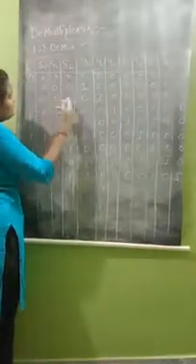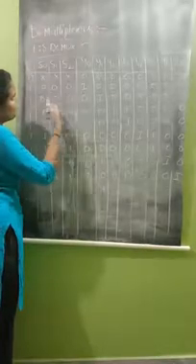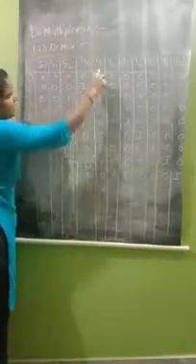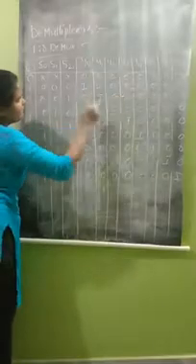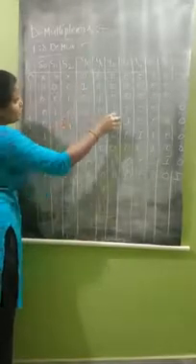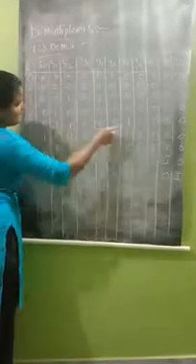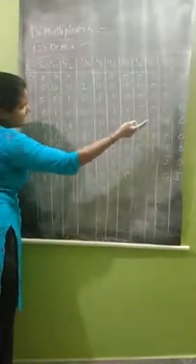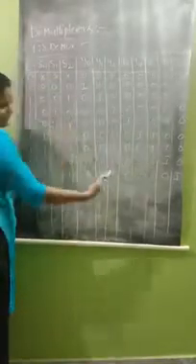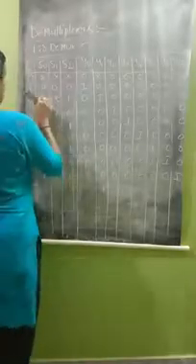Then S0, S1, S2 as 0 0 1, which means 1, so Y1 is 1 and the remaining are 0. Then 2, Y2 is enabled, then 3, Y3 is enabled, the remaining 0. So like this. This is the truth table of the 1:8 demux.